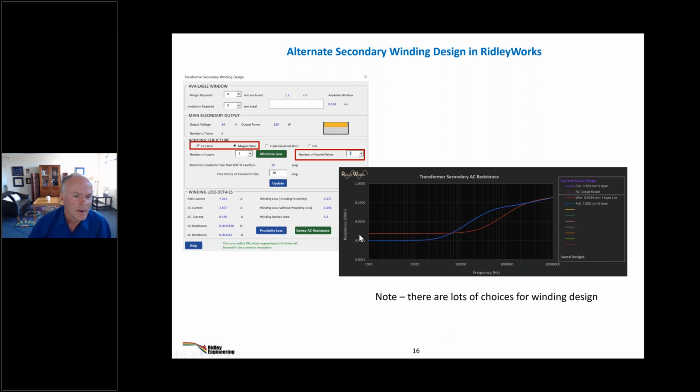Basically, I don't know the answer, and I would imagine for every application it comes out differently. What I've done over the last couple of years, if you look at every presentation out there, you will see inductor ratios going as low as 3:1 and as high as about 10:1. So that's looking at the experience of the industry. My intuition is that about a 9:1 ratio is right, but hey, this is your design freedom. Could we iterate the design 10 times and scan through those? Of course we could, but then we take away all your fun. So we're not going to do that.